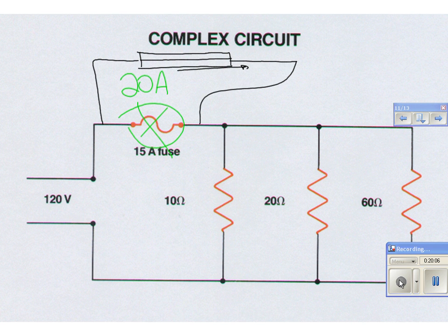It's going to bend. The strip is going to start to curve. You with me? And as it curves, if it gets hotter and hotter, eventually it'll curve so much that it breaks the circuit. Boom, circuit breaker. It breaks the circuit, no more current flows. Now they've added things to it. This is a very simplistic version.